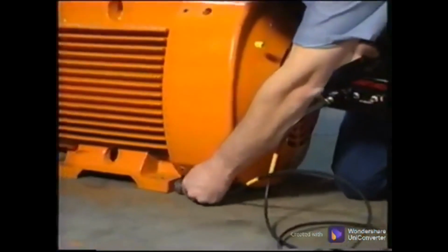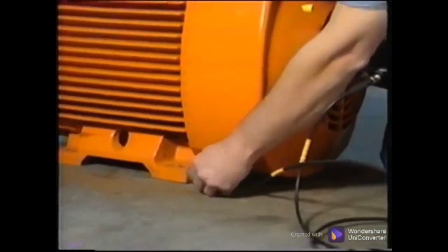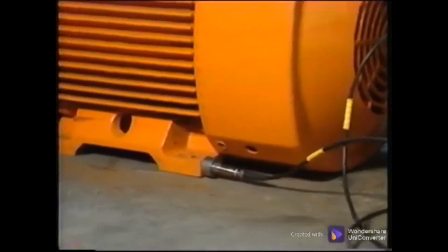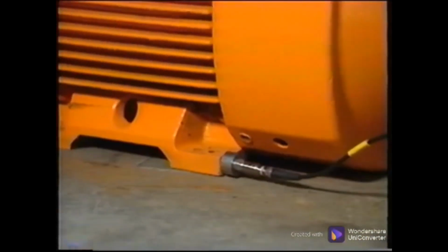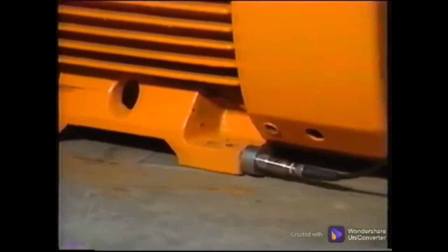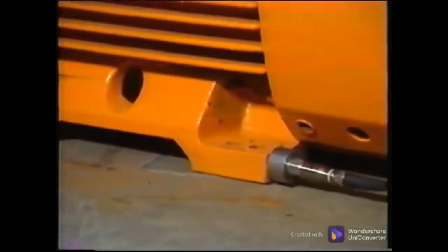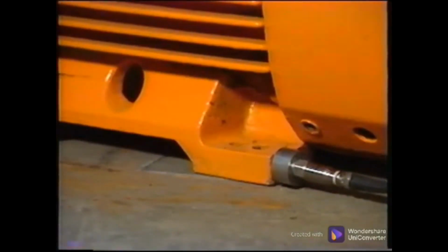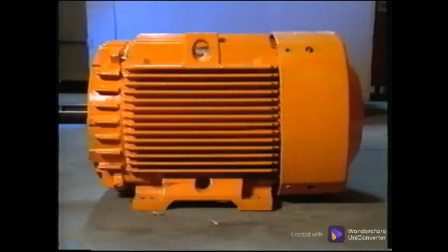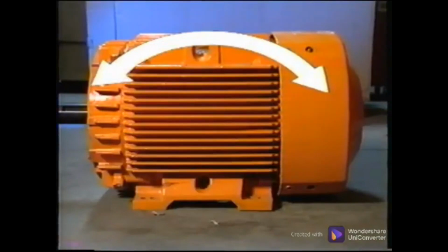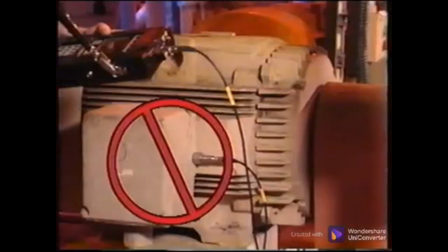The motor foot provides another location for the axial reading. If it is used for the axial measurement, the analyst needs to keep this in mind when analyzing the data. Because the foot is firmly fastened, any axial movement will be minimal. An axial reading on the lift hook would have more freedom to move and thus would have much higher levels of energy. When comparing amplitudes for radial versus axial readings, keep this in mind.